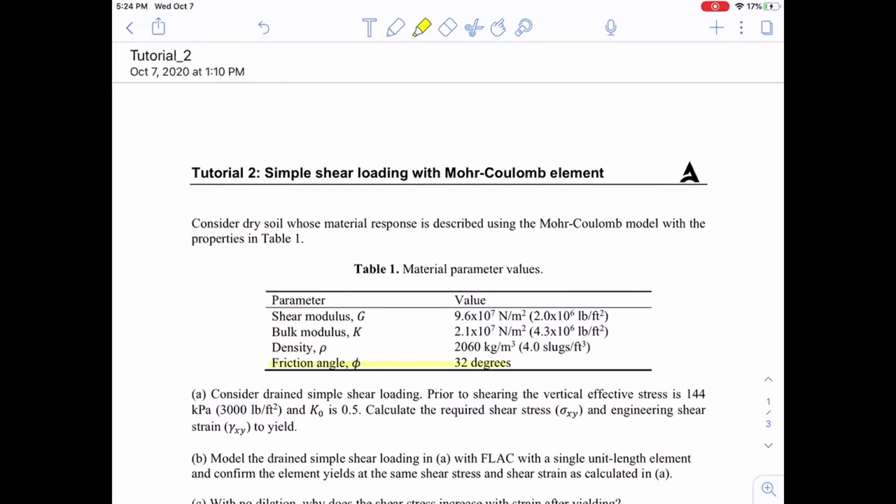There's a series of questions. The first is some hand calculations. I talked about the importance of spot checking our results, and that's going to be highlighted in A. It's also useful to calculate values ahead of time and then compare the values calculated ahead of time with those that are calculated through FLAC. In many cases, it's the other way around.